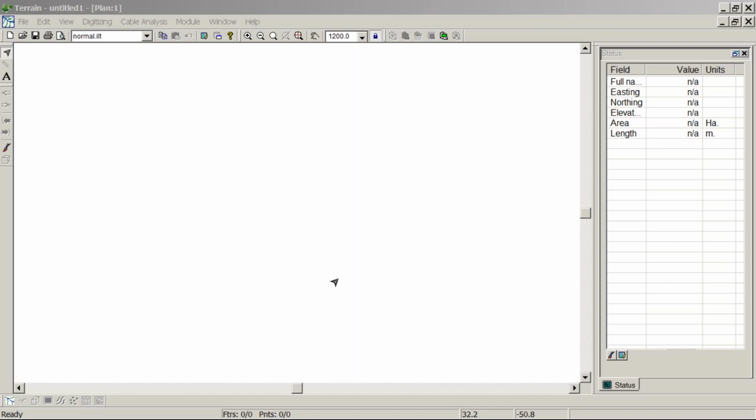I'm just going to run through the steps that I will follow. First of all, I will import some shape files that are road shape files. They have a whole bunch of roads with three roads in them, and I will then import the LiDAR data, use those roads to thin out the LiDAR data for the corridor of interest, and then TIN and model the surface. Then I will actually go and do a road design of this. A horizontal alignment, vertical alignment, and that's going to be the end of the demonstration.